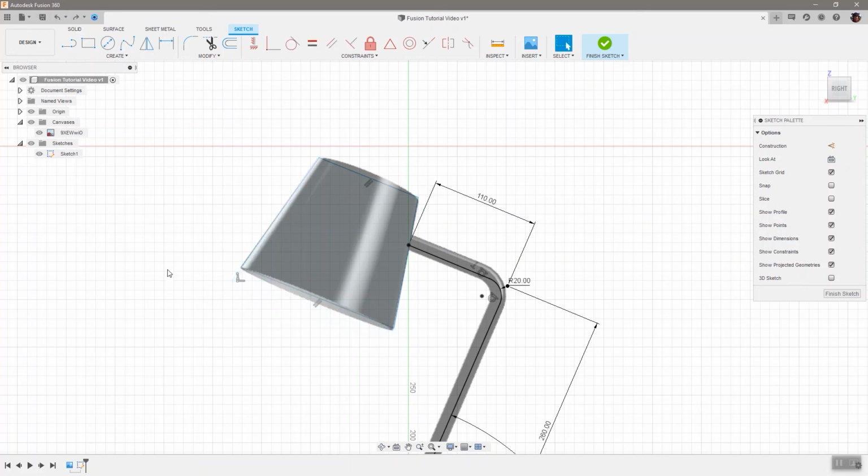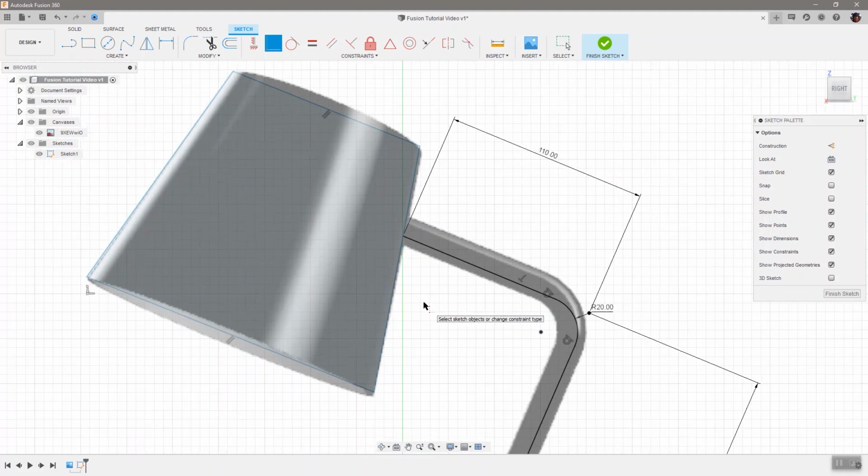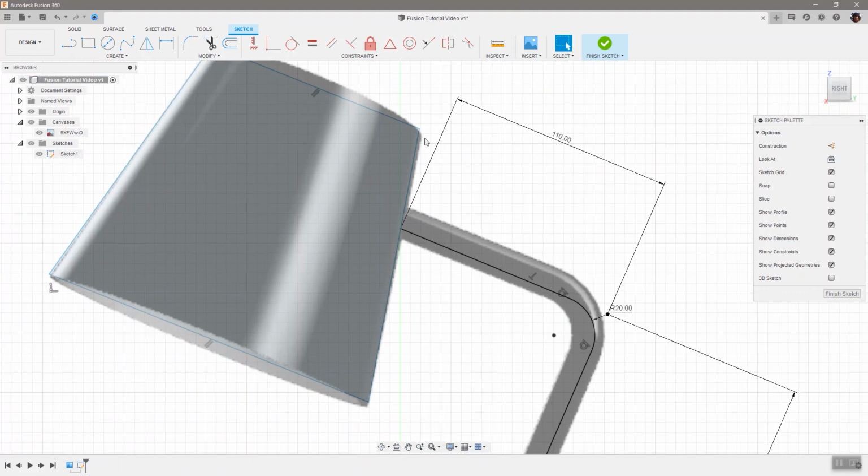So let's also think about how we're going to place this on that line. So we're going to escape command. We're going to use the coincident command. And I will say you, line, are coincident to that point. And so from now on, if I hit the escape key again, you'll notice that I can push and pull on that all I want, but it's going to remain there. Now I'm going to undo that again, make sure we get back to where we were, something like that.